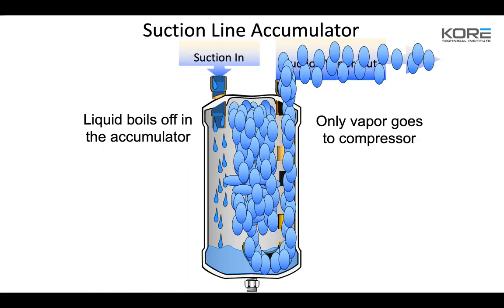Okay, because I did that one time. I knocked it off and put it back in service, and that thing immediately started to freeze all the way up that accumulator. So yeah, dragging some of the Freon out a little bit. Yeah, and again, it may be a calibration issue. So if you're frosting all the way to the top of that thing and you're doing it right out of the gate, you might do that right at first, because remember, when you first start up a system, that TXV is in what position? It's throttled all the way open. Right. So because it's trying to hit it, it's trying to get down to its set point.